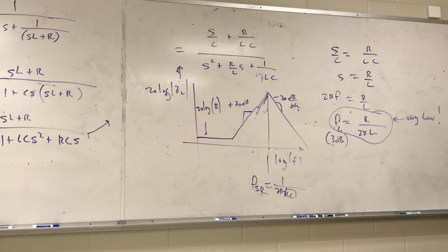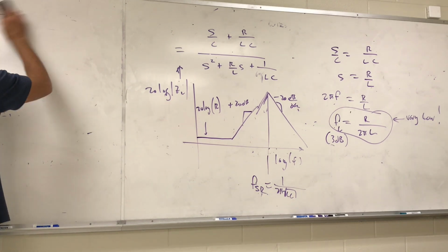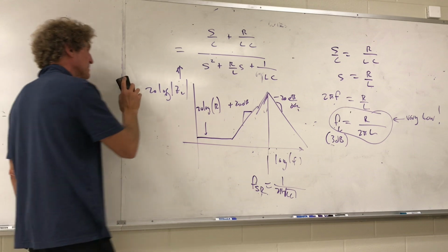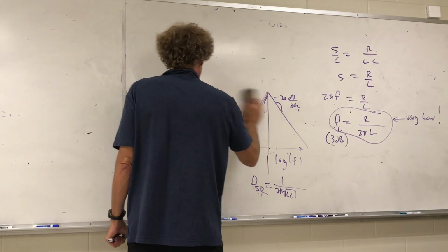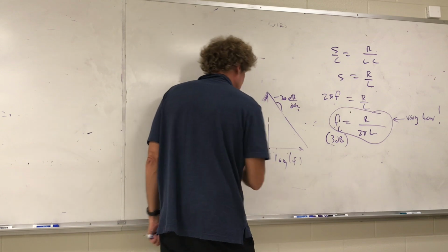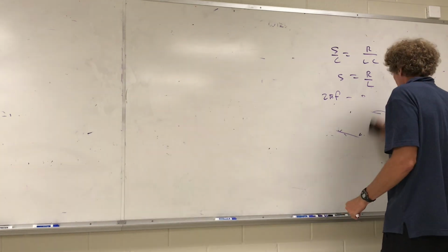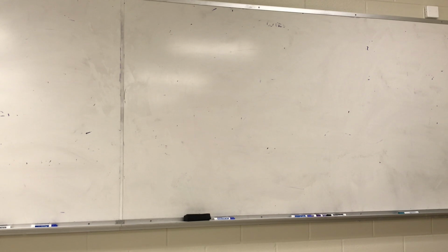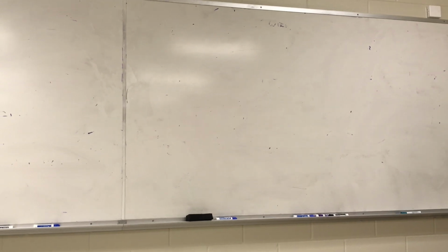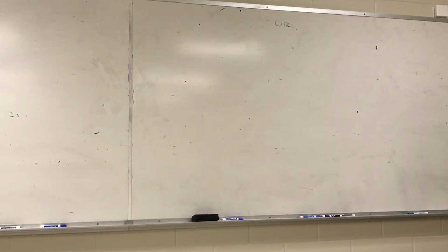Now we look at a capacitor, and then I talk about multiple wires. Now there are two different kinds of capacitors to consider. One is called an electrolytic capacitor. Anybody want to tell me what an electrolytic capacitor is versus a regular? What are some of the properties and uses? An electrolytic capacitor is a capacitor that will, generally speaking, store a lot more energy than a non-electrolytic or something with a solid dielectric. The dielectric is kind of gooey, and if you ever cut one apart, you'll know what I mean. Sort of a white goo, as I remember, for the smaller ones. But they can store a lot of energy for a given volume.